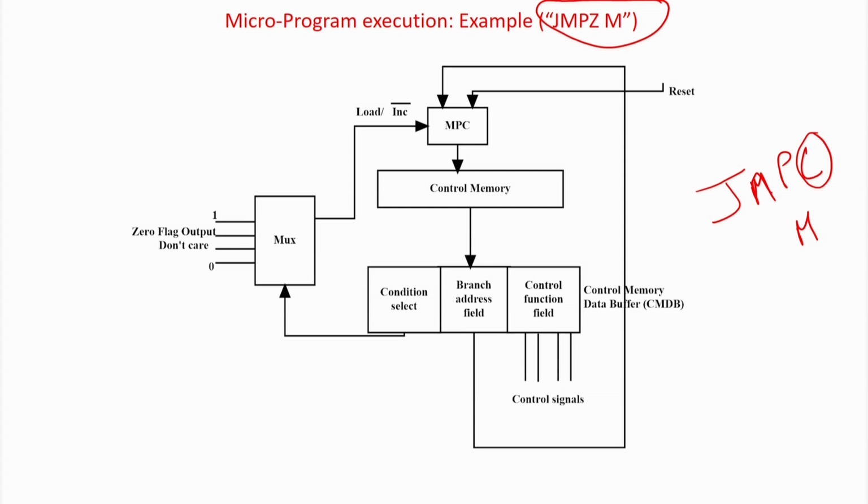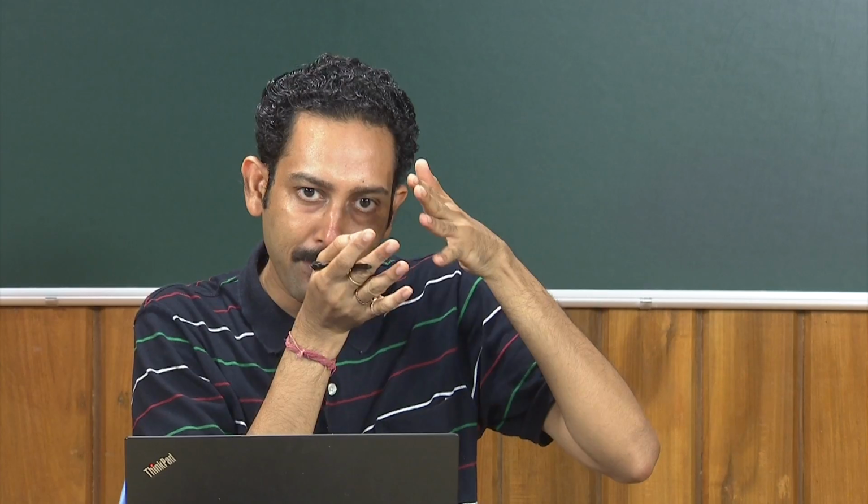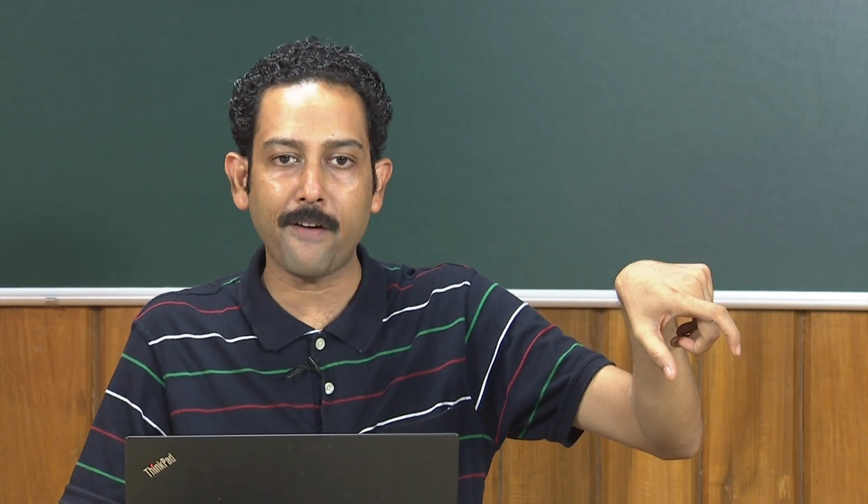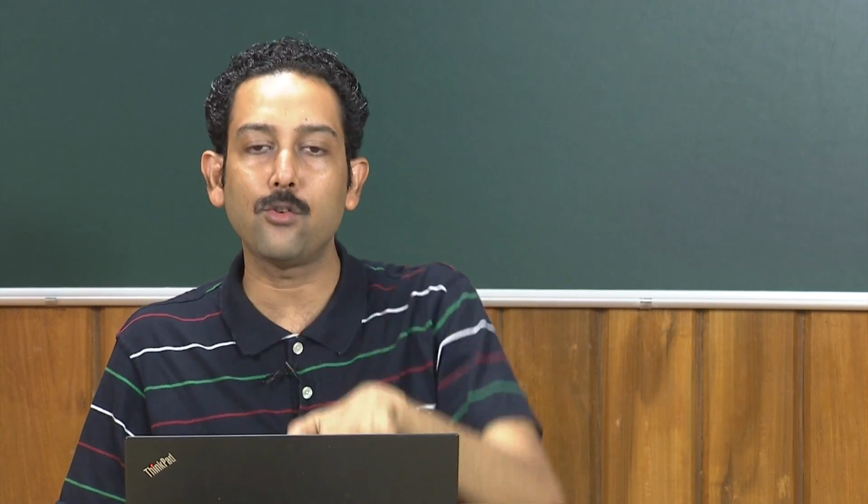Again, there is another very important thing you have to note over here. If I say that I will have a similar microprogram for different types of macro instructions which are common in type, then based on the different part you have to implement, you will jump from the main microprogram, execute the different part, and then again come back and execute the common routine.